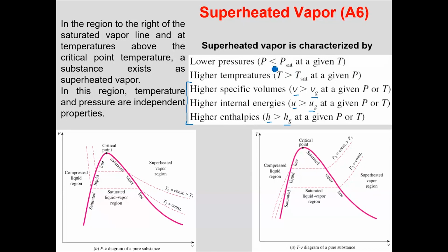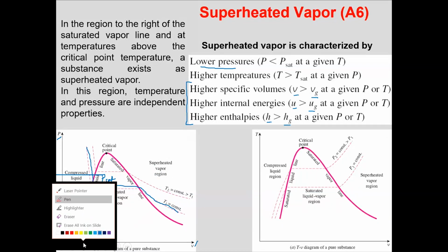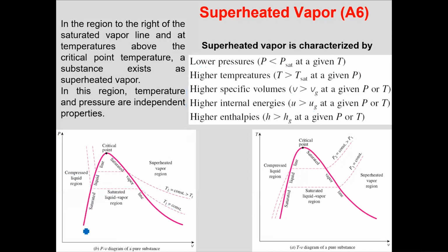Great. Now let's look at low pressures at a given temperature. Look at the pressure-specific volume plot for a constant temperature, the T1 line, the dotted line at the bottom. For a constant temperature, this pressure is the pressure required for boiling, which is known as the saturation pressure.